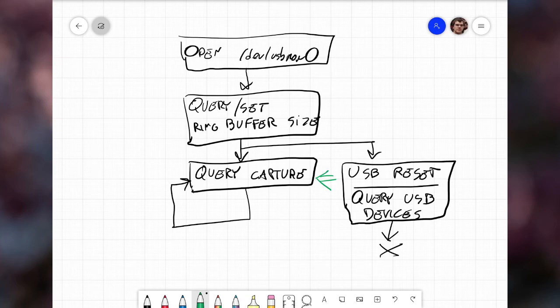If for whatever reason you start getting data in the middle of that bus reset, which I've seen happening only once, Wireshark doesn't actually know what's going on there, and it also means that you need to implement it exactly this way. If you try to implement it just by reading the documentation, you'll get a capture with all the valid data you want, but you're not going to be able to get Wireshark to tell you what's going on there. You may be able to still parse it if you know what's going on. Most of my tools just take a device address and assume that you told them to look for the right data, but there is no guarantee of that.